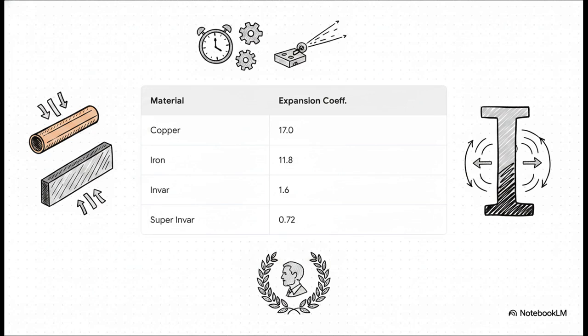Back in 1896, Charles Edouard Guillaume actually won a Nobel Prize for discovering this specific magnetic iron-nickel alloy. As INVAR heats up, its normal tendency to expand is perfectly counteracted by a contraction phenomenon tied to its ferromagnetic properties. The result? A near-zero expansion coefficient. It's a total game-changer for things like precision clocks and lasers, where even a microscopic shift ruins the whole shebang.